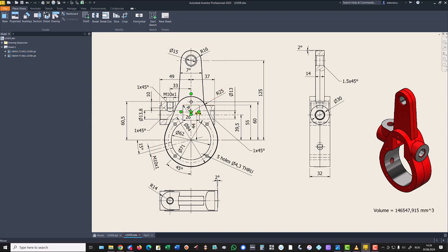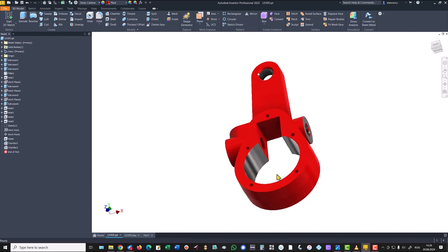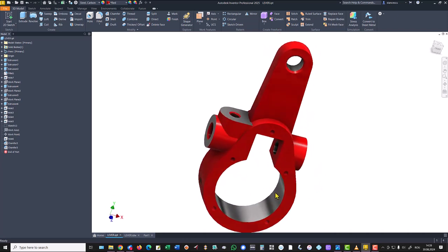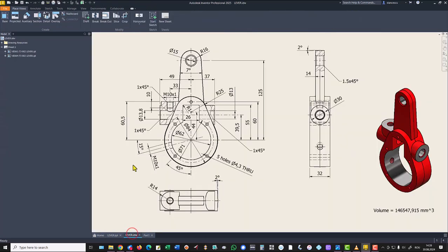Next is this internal void. You see here. You can also see the part. This contour has dimensions, of course. What dimensions? Well, this is diameter of 62, 26, and the distance of 55 here. Don't forget, there are two fillets, radius 1 here.